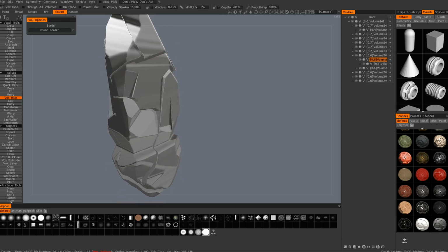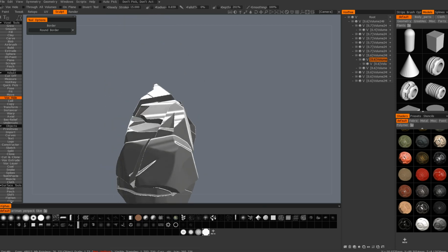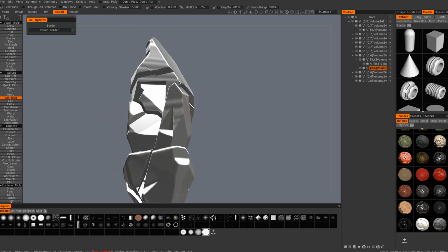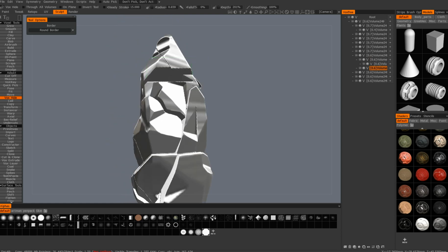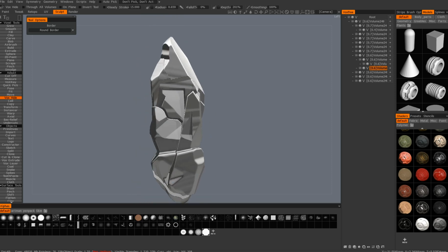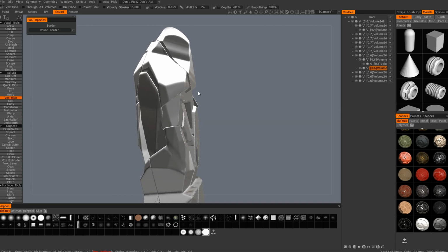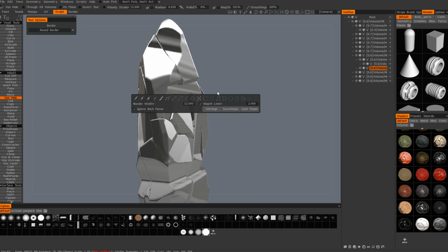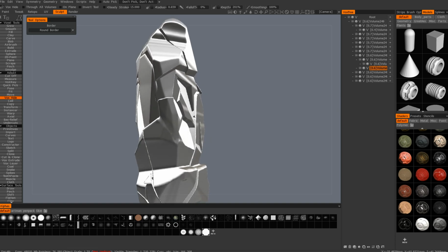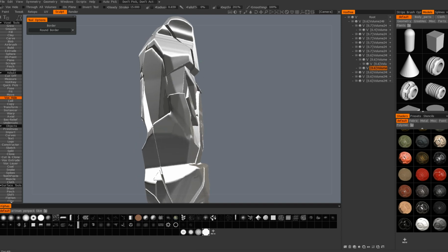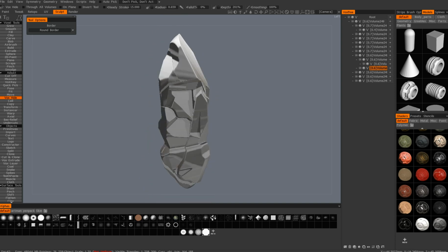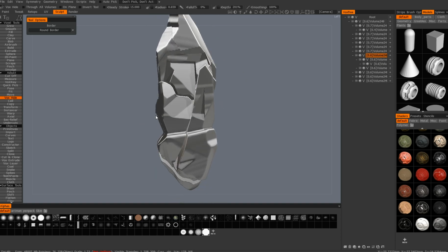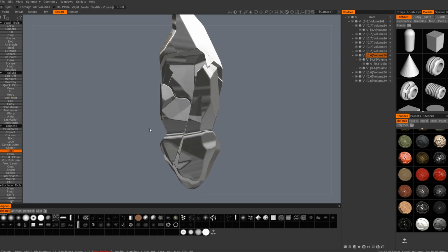I think I got the depth limit on this guy. Well, that's alright. I've just switched to rectangular, and just experimenting, really, seeing how the rectangular looks. I mean, this freedom of the sculpting is so cool. It's so much better than what you can do with a clipping or trimming brush, or really clipping brush in ZBrush. Just turn on the depth limit and cut. So I feel like there are a few cracks that would be great to have here.